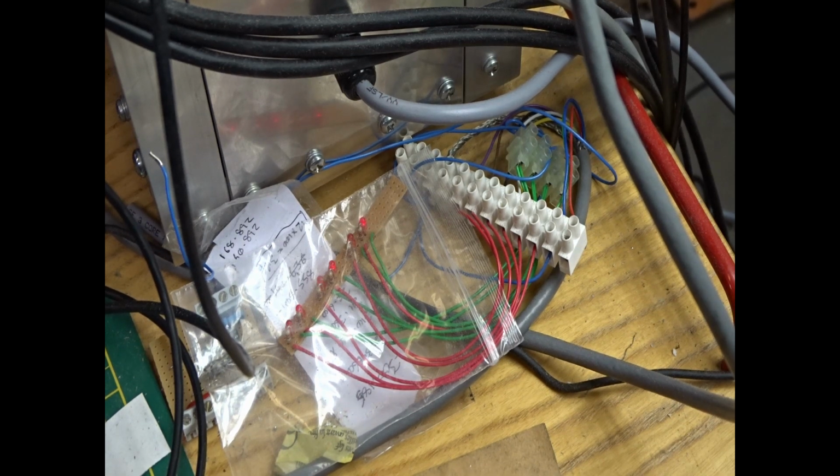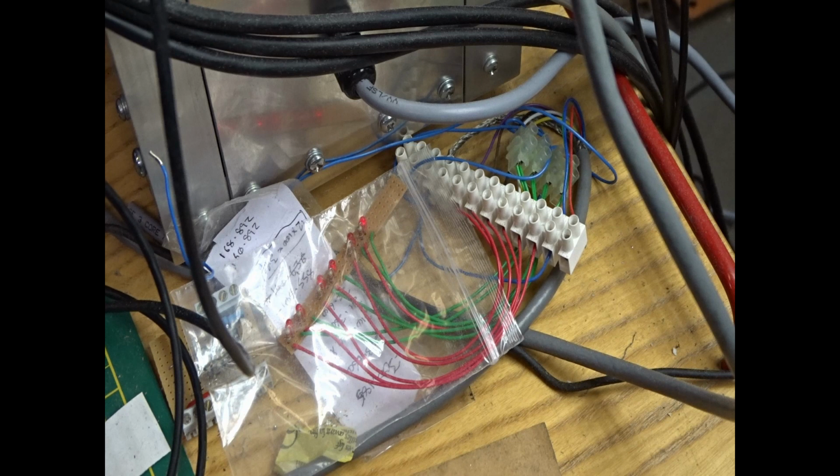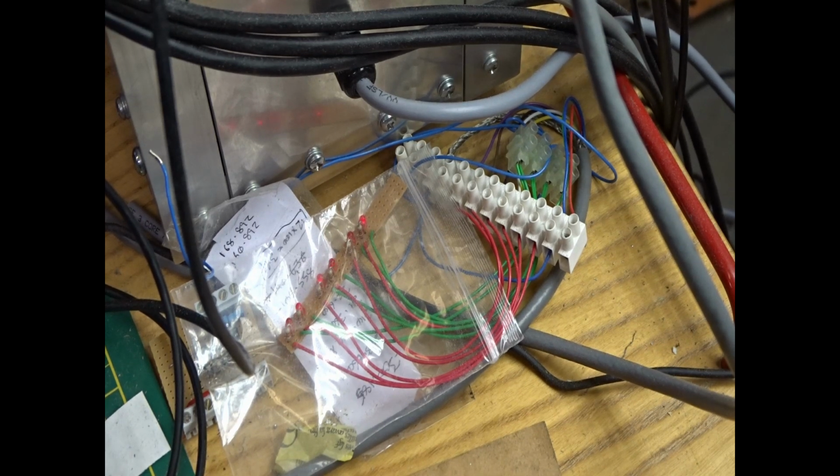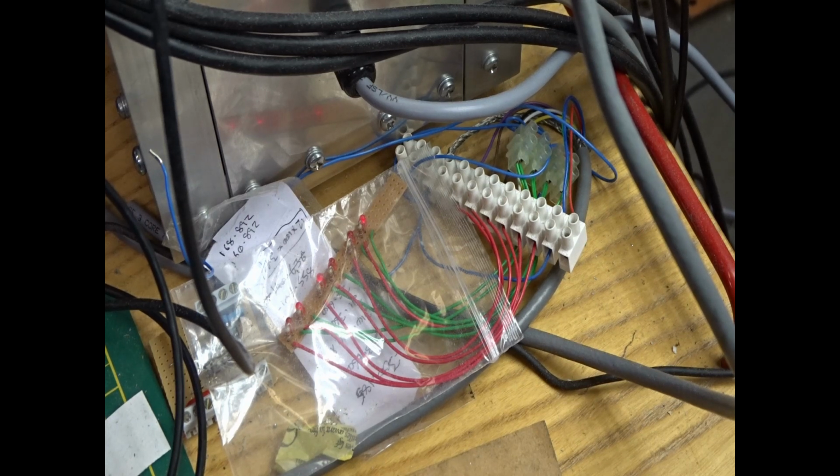I may want to break out those signals anyway for indexing. If I want to lock the chuck at a particular number of degrees rather than using the big telly, I could put in an LCD to be able to get me 5 degrees, 10 degrees, or however many degrees I want, and then put a brake on the chuck to lock it manually so that I can work on it if I connect a powered spindle to the tool post, which is possible at some stage.